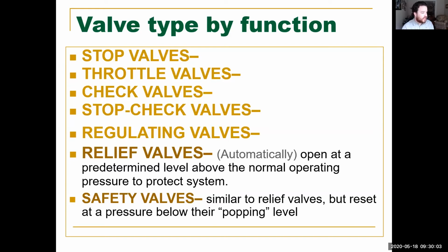But a few seconds later, because we haven't fixed the actual problem, it's just going to pop again because it's going to go up to 100. And that's why you're going to hear what's called chatter. You're going to hear a relief valve popping, opening and closing, because it's sitting right at the level that it's going to pop. All right.